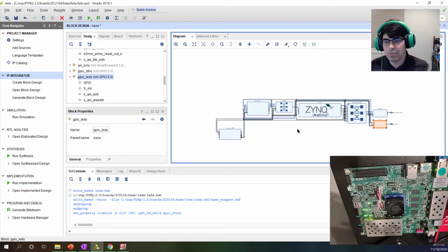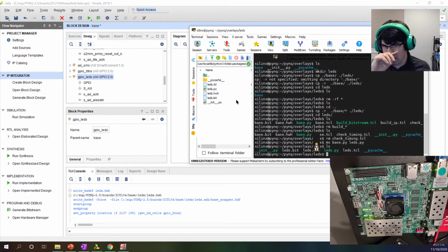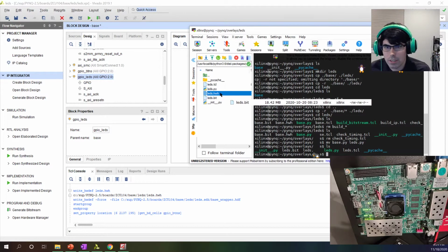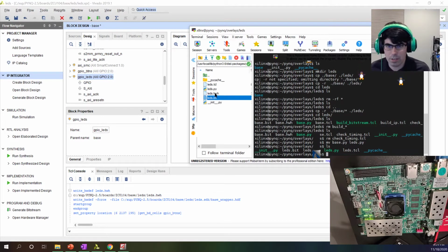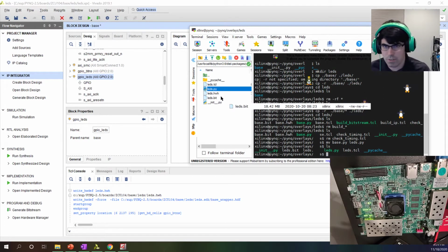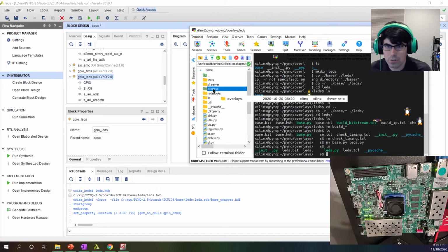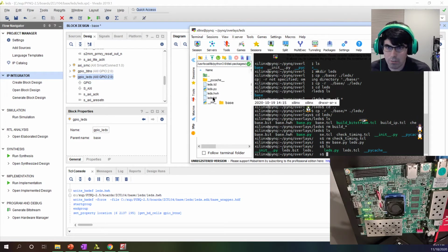We go ahead and just generate the bitstream as normal. I named these LEDs. It's DMA, but we named it LEDs. The files you need are the LEDs bit file, the LEDs hardware handoff file, and I'll show you the Python file. It's really simple. I just copied the base overlay and removed some stuff. And an __init__.py, and you just have this in the overlay folder under the PYNQ folders. It's not too hard to figure out where to put this.